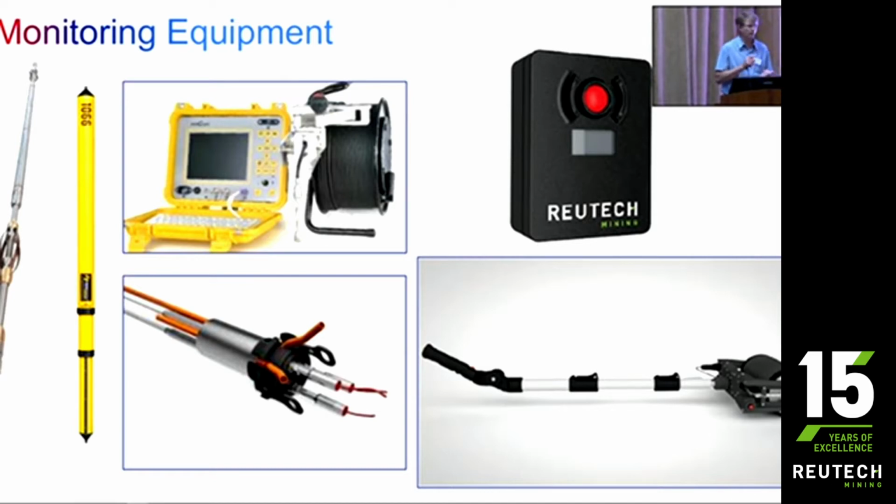You get information on rock mass strengths. You can get information on magnitude and orientation of stresses. There's a lot of knowledge and skills outside of South Africa in the oil and gas industry that uses these techniques regularly, and for some reason we've never used it in South Africa.